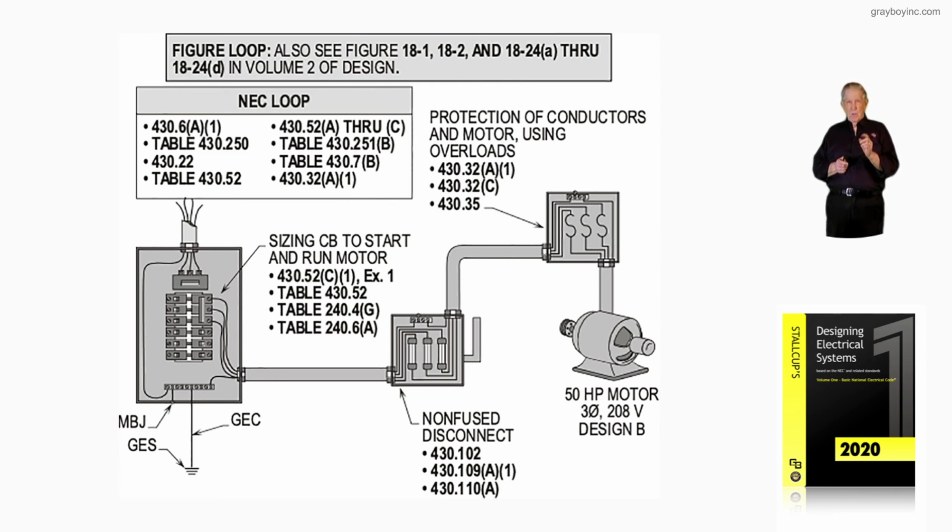But any increment moving up on your overload relay will start your motor. That's where you stop. You just don't automatically put the max in. And then 430.35 is dealing when you just completely bypass the overload protection to allow the motor to start, run, and operate, and then naturally the overload is put back in when the motor is in its run position.